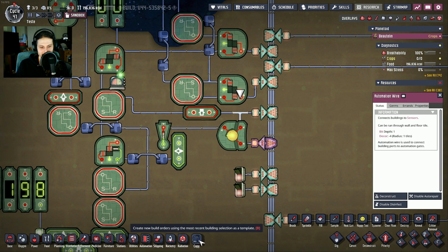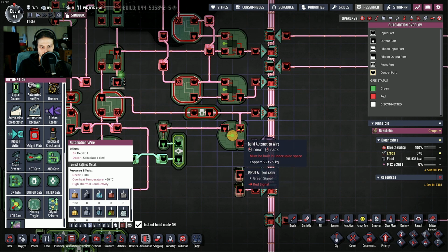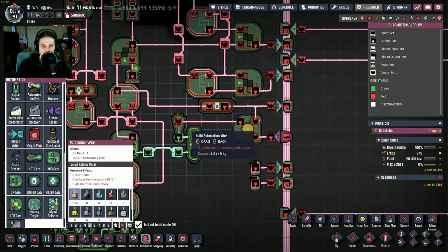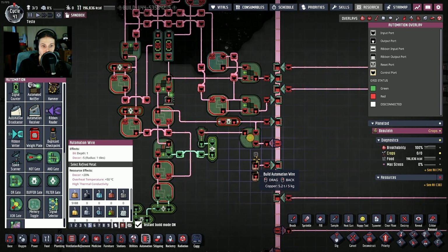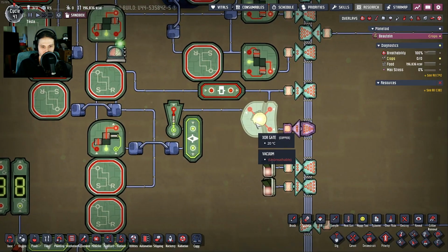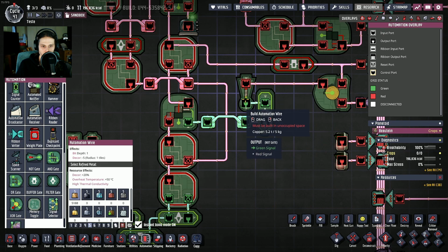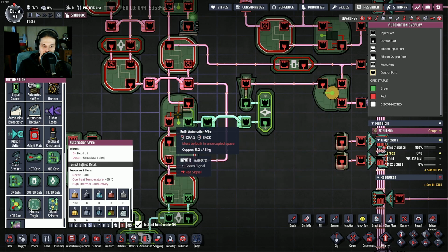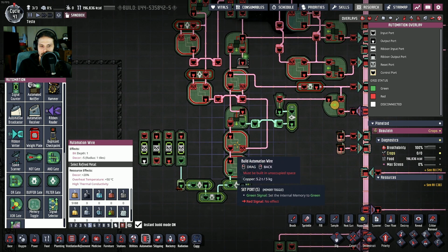And this is going to read from both the internal line and from bit 3. What does this mean? If both this and this are green at the same time, that means that I am the one writing, right? Therefore, this is going to turn red, which in turn is going to send a green signal through this NOT gate, allowing the AND gate over here to let the pulse from the waiting memory toggle to pass through.